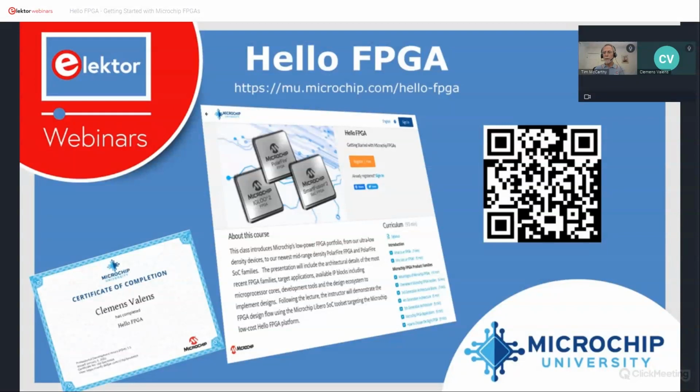Okay, thank you. Is flash-based FPGA boot almost instant compared to non-flash? So you saw a slide that compared the interconnect technologies. The most popular type is SRAM, but SRAM is volatile. So when the device boots up, you have to configure it every single time.